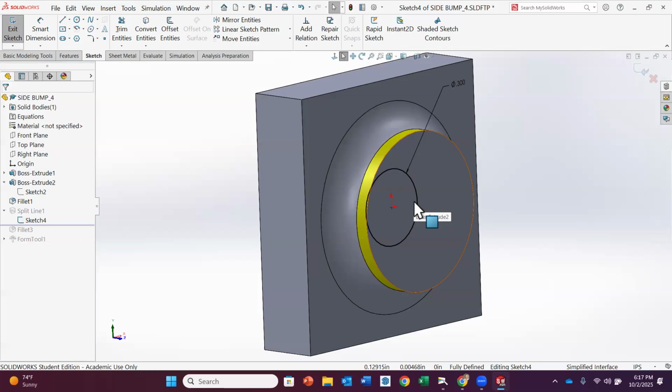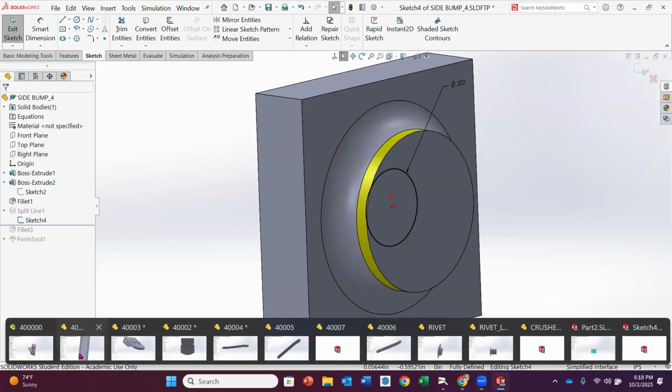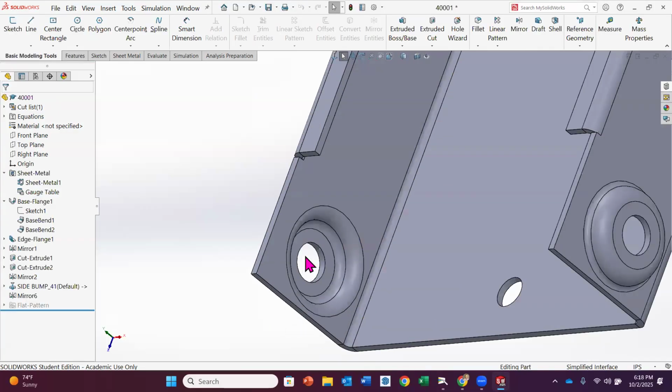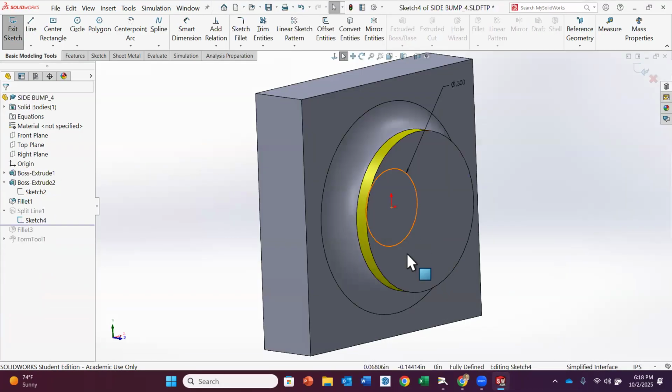The reason we have to do that is because the split line splits that surface so that it'll know to put a hole in the middle. That's what you did in your tutorial, except it was that arc. This is now the hole, because this is representing where we're going to be putting a hole through there. So I needed to form and cut. Again, this form tool is not going to be used in manufacturing. This is not how they're going to do it. This is just so SolidWorks knows what to do to represent this.